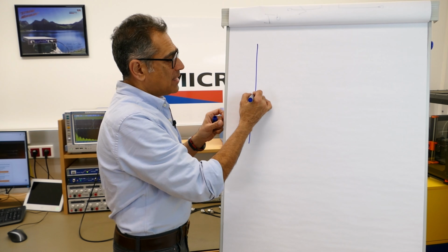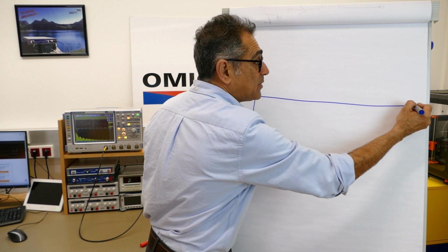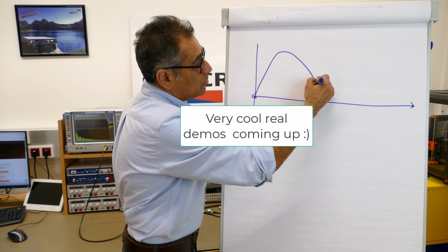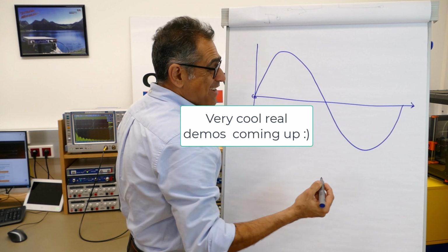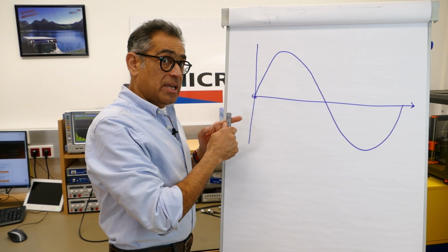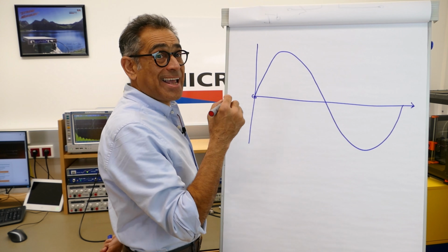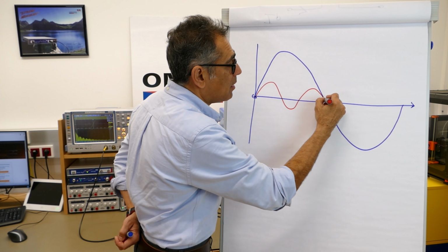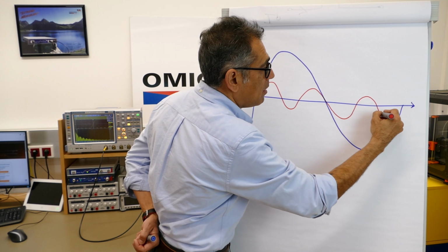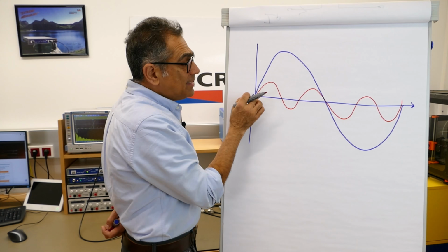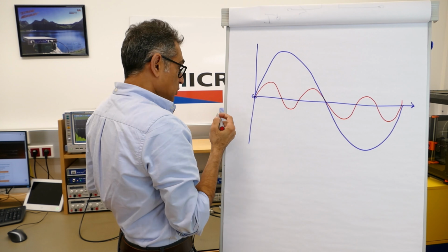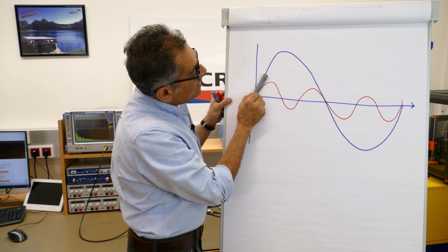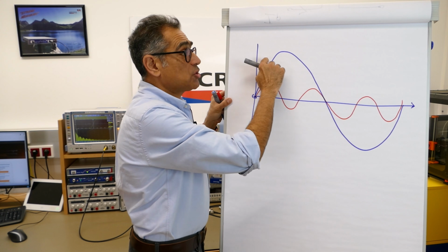Let us say that I just have a sine wave. For simplicity, let me say that is 100 kilohertz, and I'm going to draw it like so. This is my 100 kilohertz. A power supply is not a sine wave, it's a square wave. Now, if I take this sine wave and I add a third harmonic to it, so if that's 100 kilohertz, this will be 300 kilohertz, the addition of this third harmonic to this fundamental will give me a resultant whose rising edge is sharper and its top is a little bit flatter.